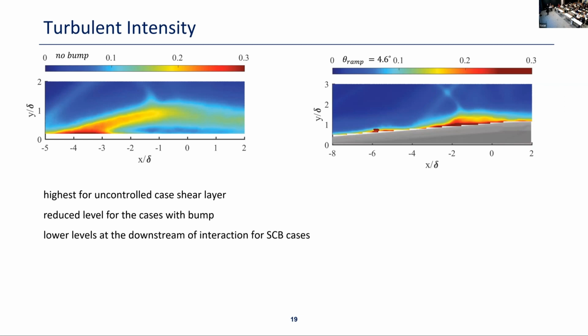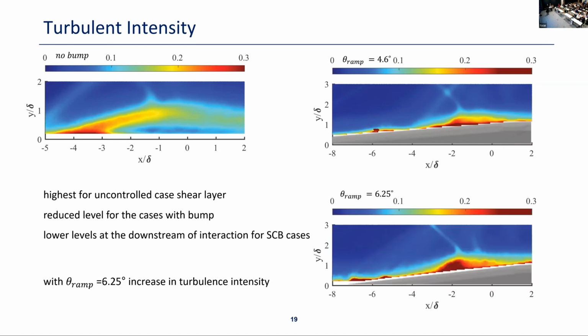Also, we can slightly see the leading edge effect, and the interaction part is kind of reduced. But when we look at the 6-degree case, there is this part, which could again be some effect of the bump design. And we see there is no clear separation shock foot, but it's more like waves. So this is definitely an interesting case for understanding the effects of these parameters.